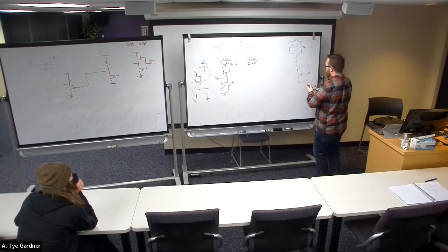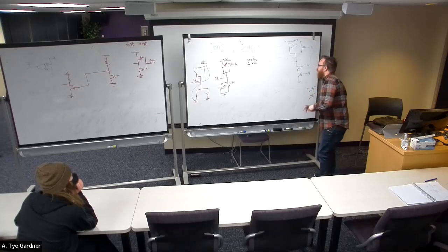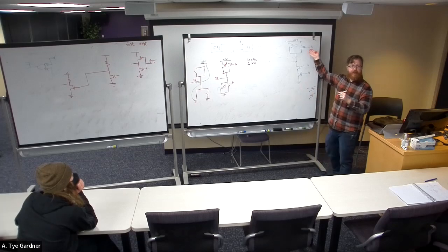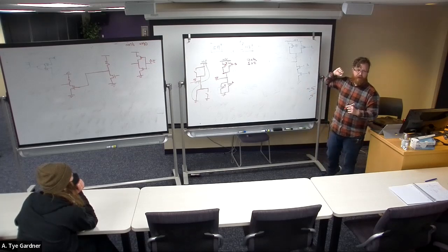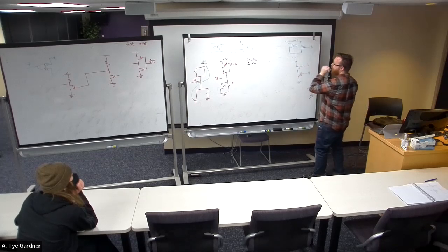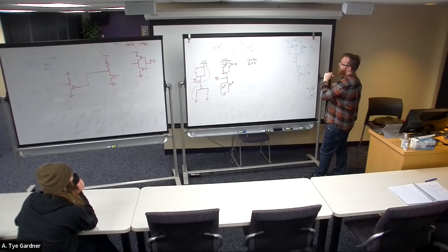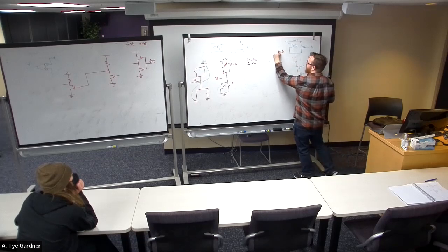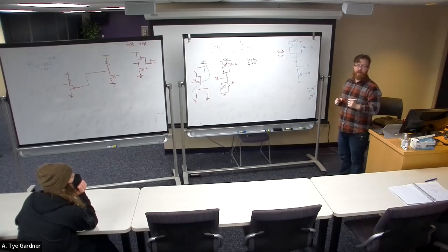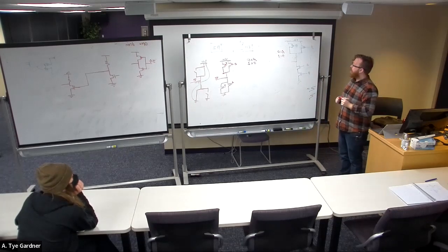So let's do a situation where, what's an input combination that confuses you about how it gets the result? For at least this one, if you say 0, 1. Okay, so A equals 0, B equals 1. Because at that point you get the signal from power being 1, and then you get an open circuit to ground.